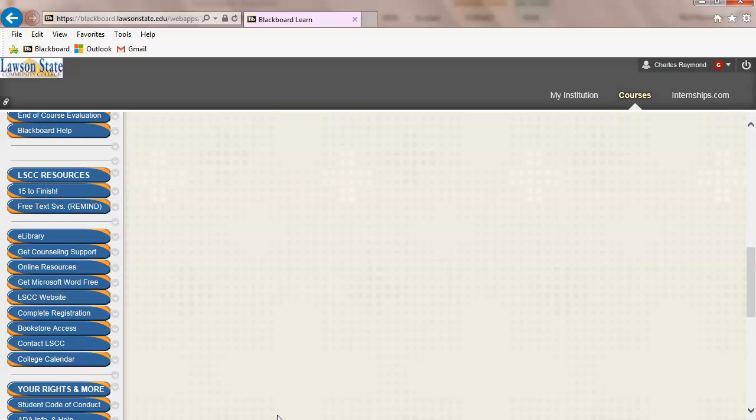So even though the tip switch is actually operating off of 24 volts DC, its outputs are going to pick up relays. And what can we put across those contacts? We can put 120 volts AC across those contacts. So guys, computers aren't doing away with relays. They do away with a lot of them, but they don't do away with them.